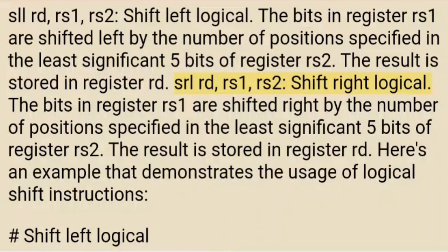SRL rd, rs1, rs2: shift right logical. The bits in register rs1 are shifted right by the number of positions specified in the least significant 5 bits of register rs2. The result is stored in register rd.